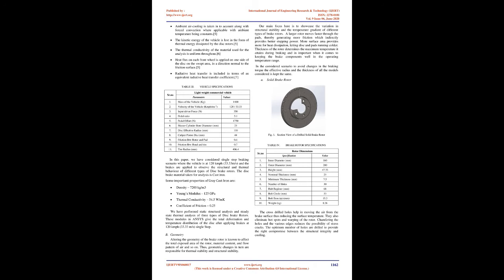5. Material analysis. Material requirement for disc brake rotor, as based on the functionality and its possible defects, material properties are needed to take into consideration. Disc brake rotor material needs high strength and high stiffness even at elevated temperatures because of high amount of heat generated due to friction of the brake pad. It should have low density and high thermal conductivity to easily dissipate heat. Also, the material needs excellent abrasion resistance and good creep resistance.